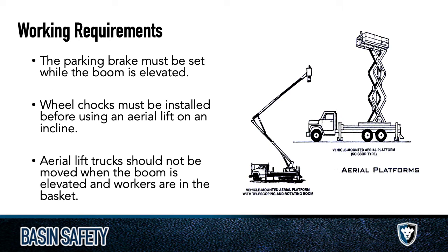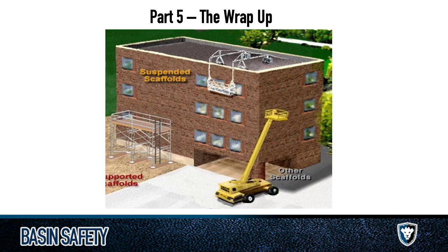Working requirements. The parking brake must be set while the boom's elevated. Keep that in mind. A lot of them do that automatically. Once you stop and start moving the boom, the parking brake on the wheels automatically sets. If you're on an incline, just like a forklift, you need to use your wheel chock. And aerial lift trucks should not be moved when the boom is elevated. Not a good idea. Don't do it. Bad practice. Terrible, terrible idea.